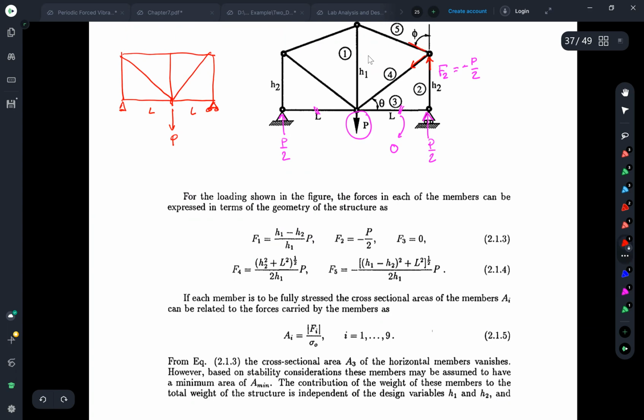it's a tension in member 4 and member 5, with F4 and F5 in equilibrium at this node, right? This joint. Therefore, you have to take the equilibrium of the horizontal force and the vertical force, and with the equilibrium of the two components, you have two unknowns, F4 and F5.